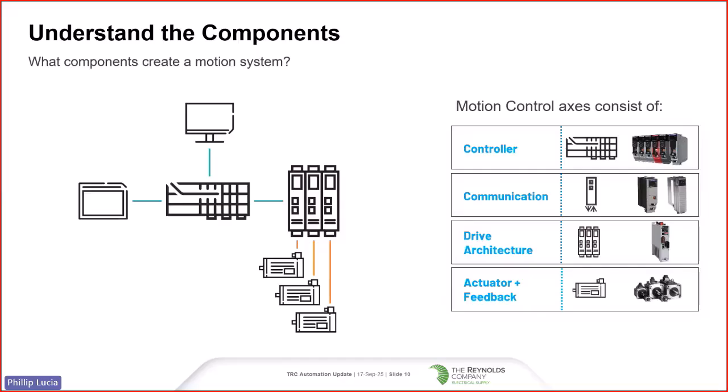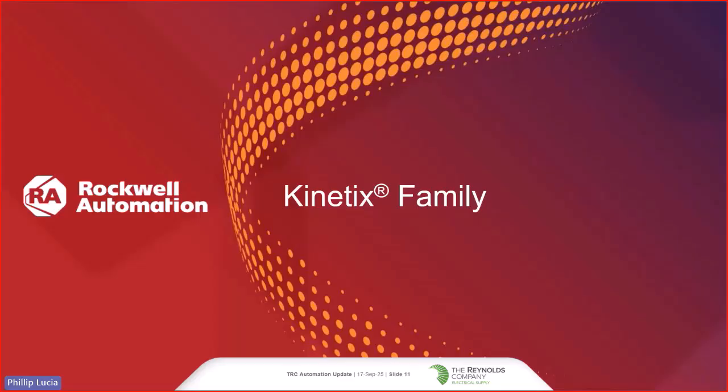Now, while each of these components should be selected carefully, you always start with your actuator first. If the actuator can't deliver the performance that the application needs, then the drive and controller will not be able to make up the difference. The mechanical requirements drive all the other system design considerations in mechatronics. That's an important point to be aware of.